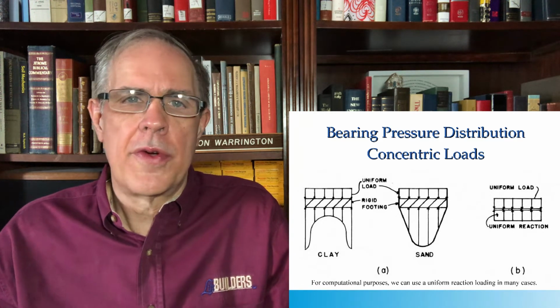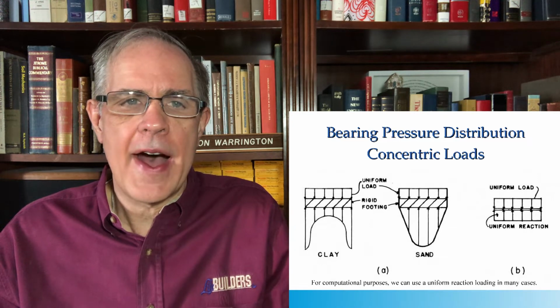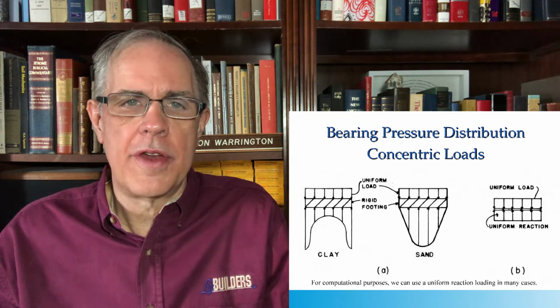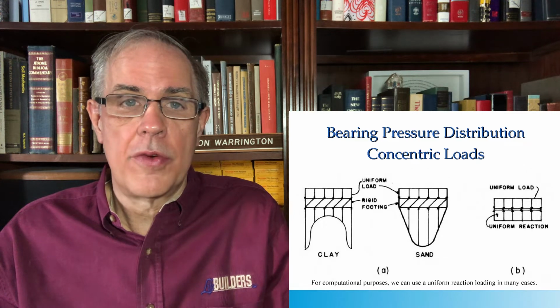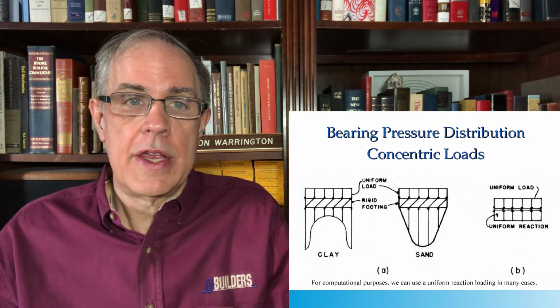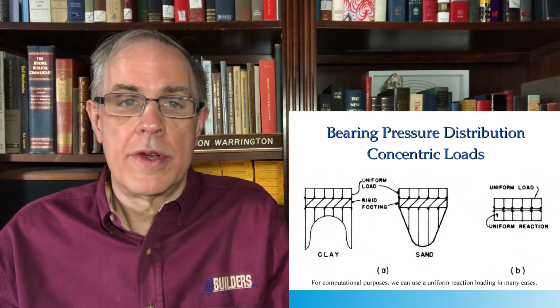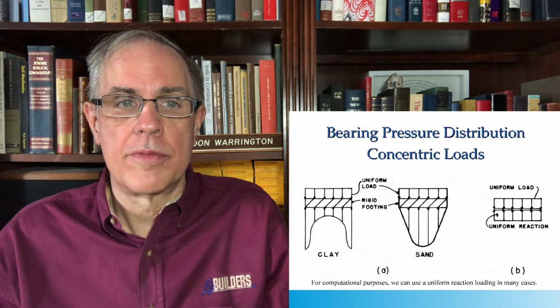In a clay soil, it's more like elastic theory predicts, where you've got a very high load in the corners of the foundation and a low one at the center. Whereas with a sandy soil where friction dominates, it starts at zero and goes to the high point in the center. So it does not follow the theory of elasticity solution.